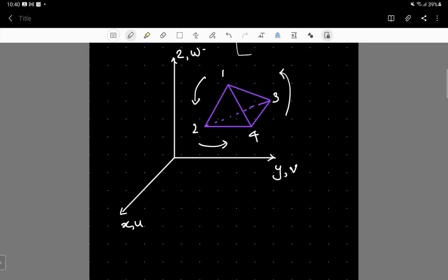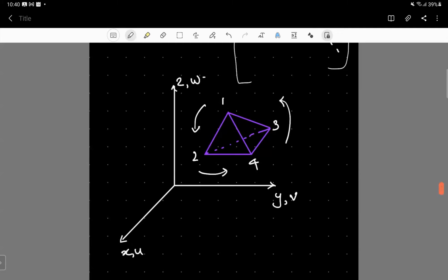If we are deriving this matrix using an isoparametric formulation with the natural coordinate system, the numbering method is irrelevant. It doesn't matter whether you number them in the counterclockwise or clockwise direction, you would get the correct results. But here in the global coordinate system, it is important to number them in the counterclockwise direction, especially when viewed from the last node.